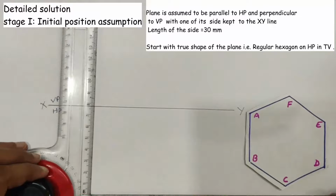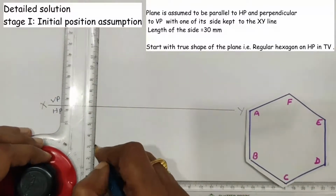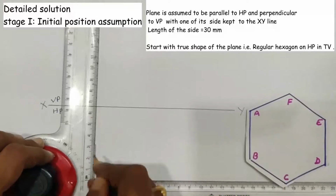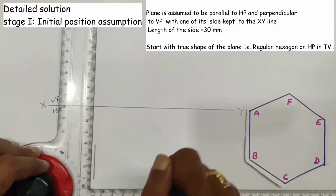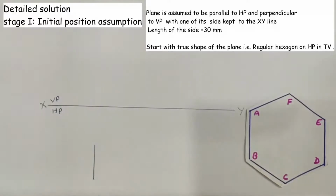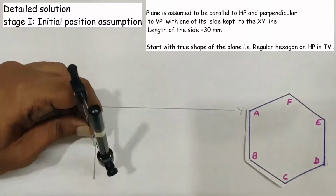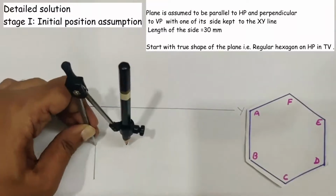Draw the side of the hexagon, say AB, which is perpendicular to the XY line. Then complete the construction of the hexagon using the circular method. For that, take the side length as a radius and one end of the side as a center.